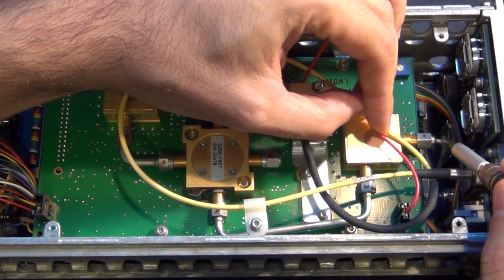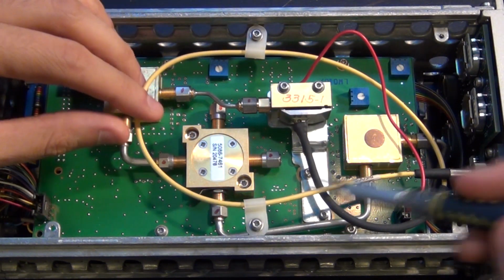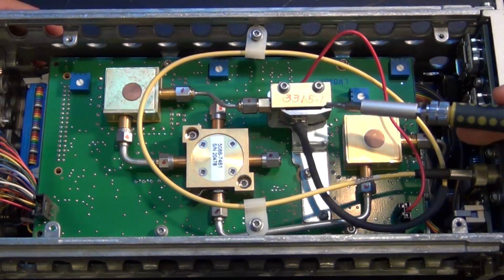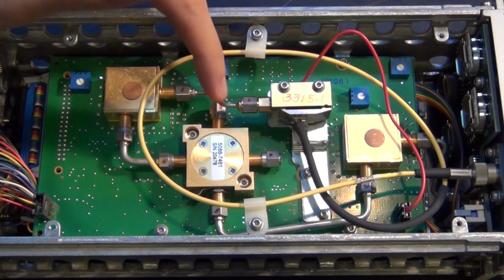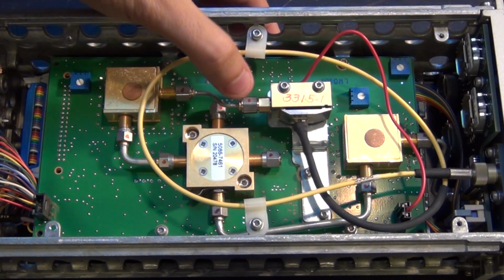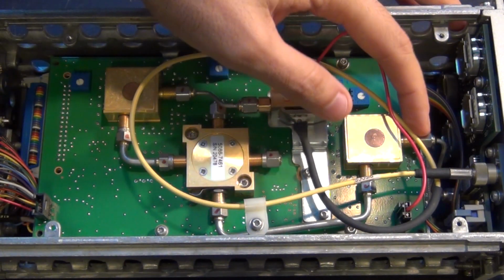And that one is connected to this over here. So we have our analog 50 gig input, we have our fiber coming in, and this yellow cable is a fiber optic cable. And if you follow that, you can see that it goes into this module, and this module is a photodetector, so it does optical to electrical conversion, and the signal coming out of here is a direct detected signal based on the optics input, and this is also an electrical signal now, which is very similar to the signal over here.